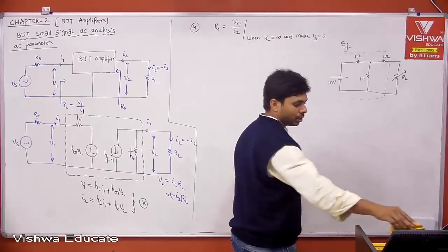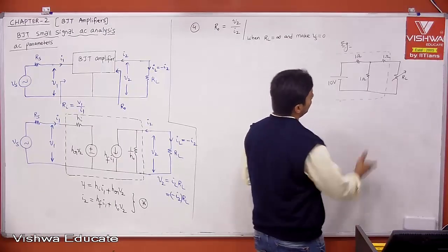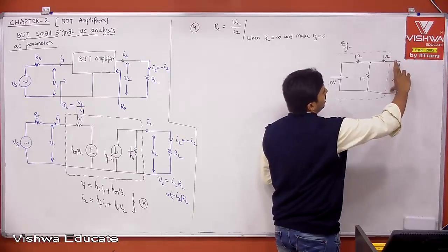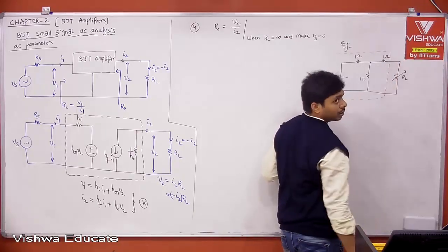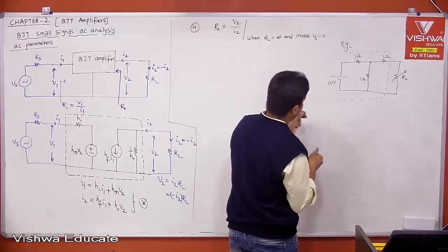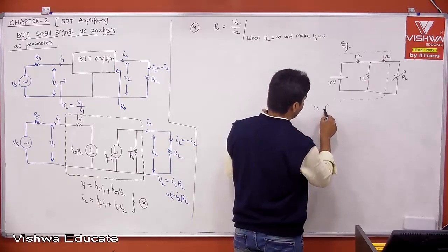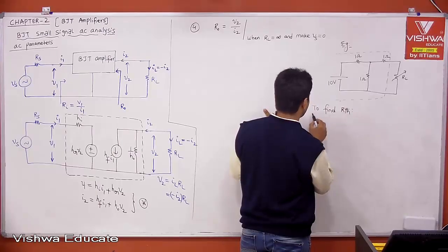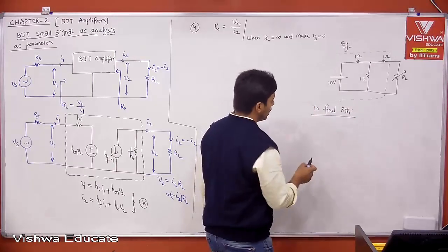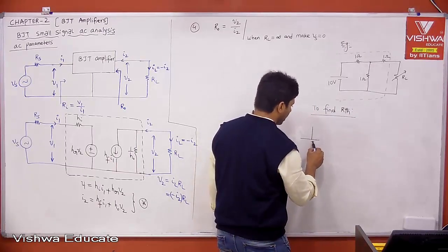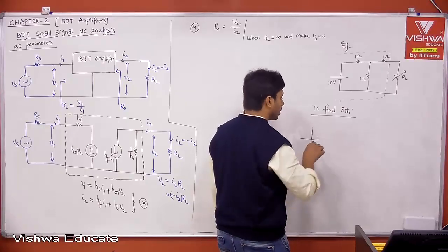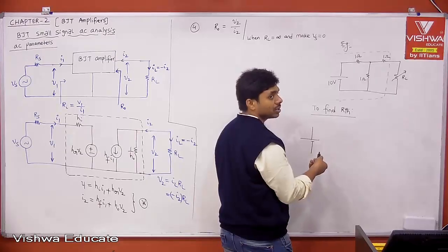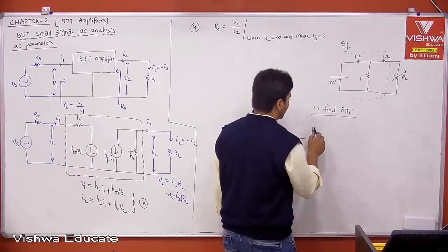Now, from the original circuit, what is R Thevenin? After excluding the load, the effective impedance seen from the output port, right? Therefore, to find R Thevenin without any methodology. Now, just listen. This is the battery. I am not replacing the battery with 0, right? But effectively, if you replace the battery with 0, whatever you get, that is what you will get. That's why people define a methodology which is easier. But why it is a short, I am explaining.